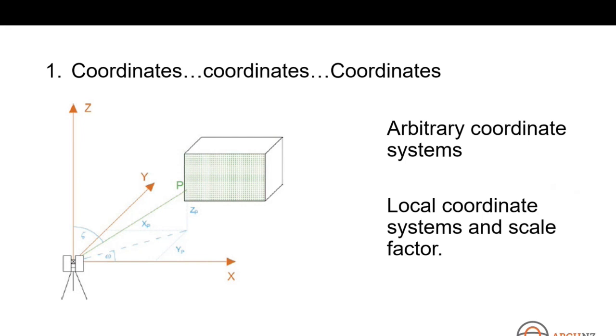And beyond that, with ground-based laser scanning, the view of many companies dealing with laser scanners is that they are inherently more accurate to go out and do your ground-based measurements, so they don't account for scale factor, which means that if you're doing really long sites, scale factor can become a bit of an issue with how you're applying coordinate systems into your data if you want to view it in a GIS system.